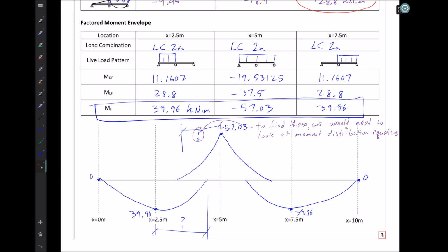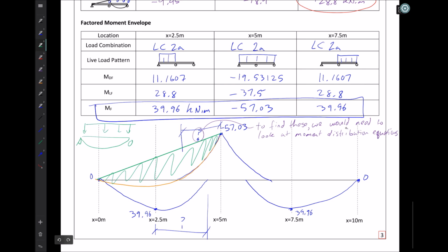Now, one thing that I would point out at this stage is that if I was to carry this over to there, I could figure some stuff out from this pretty easily, because the shape that I'm about to shade in here is equal to a shape here where this is a simply supported beam under uniformly distributed load with the addition of an end moment M. And this would leave us with a moment diagram that would look like this on that beam.